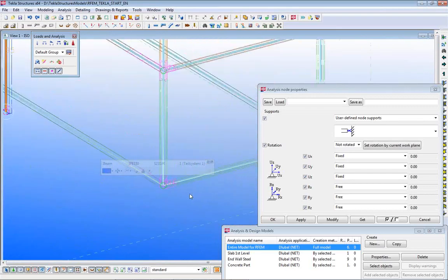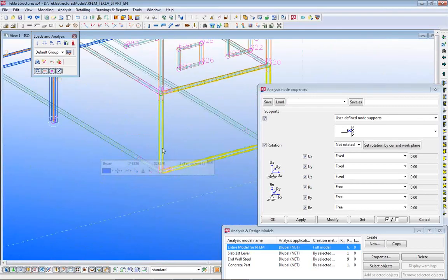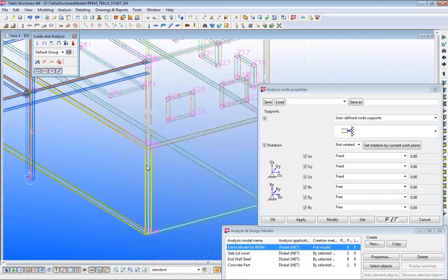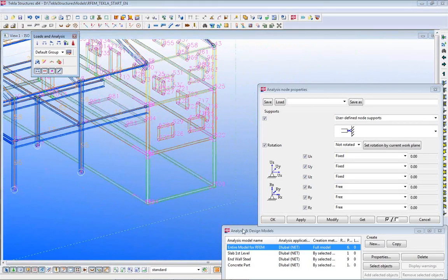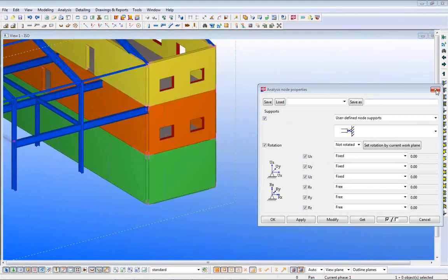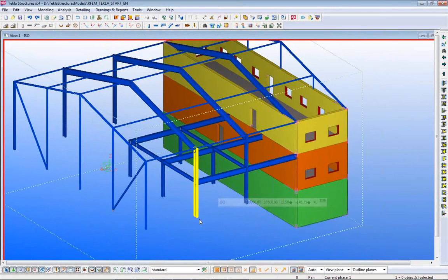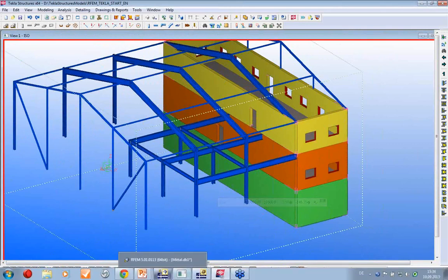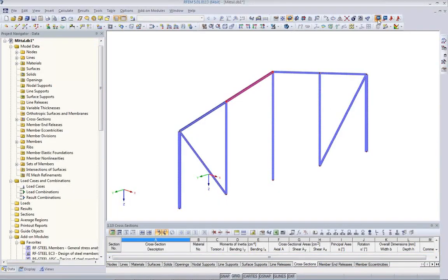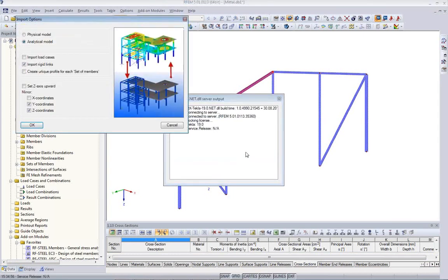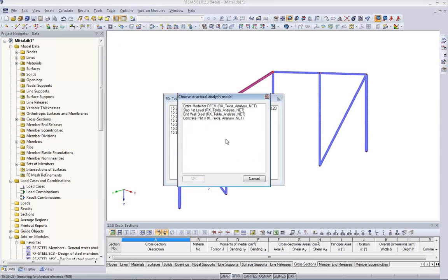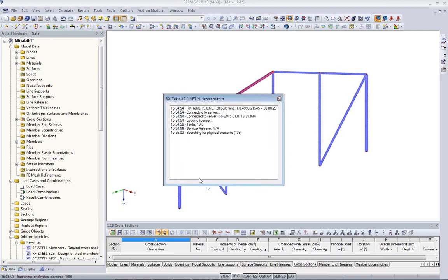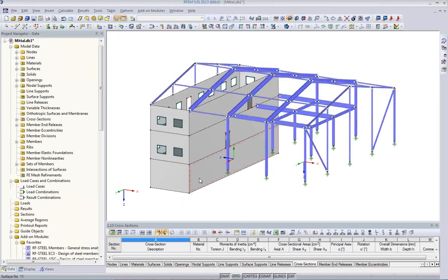Okay, also here the walls are modeled as center lines and the slabs as well. So I'm closing the model here and stay with the physical model view, and I start inside RFEM and I import the analytical model, including rigid links, which I don't have at the moment, and I click OK. So now I choose the entire model, click OK, and we are importing the entire structure.